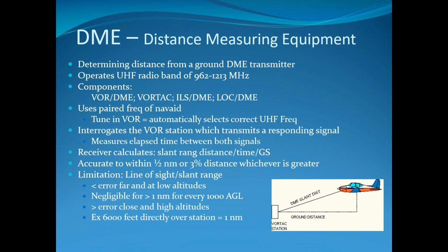See, one problem with a VOR DME system is if you are flying at 35,000 feet over a VOR, then your DME equipment is never going to tell you that you're closer than like 7 miles because you're 7 miles straight above it, right? So once you get high enough and you're right straight over a VOR, it becomes less accurate.